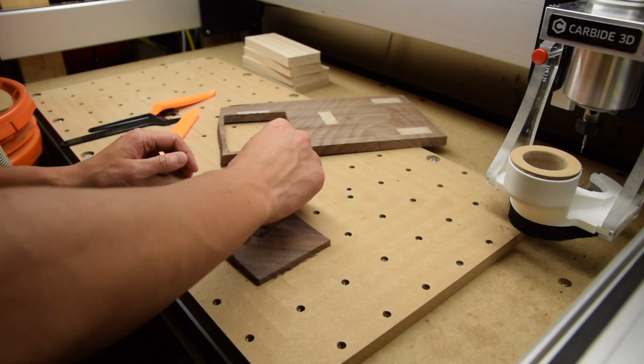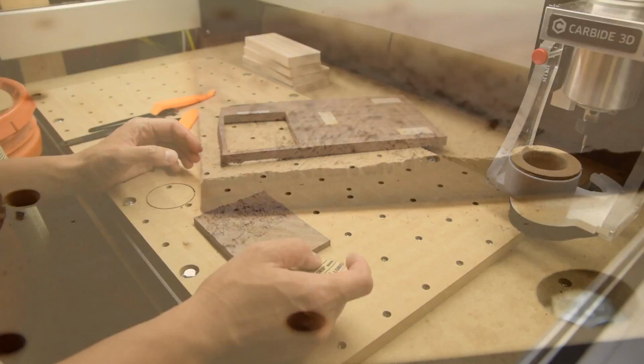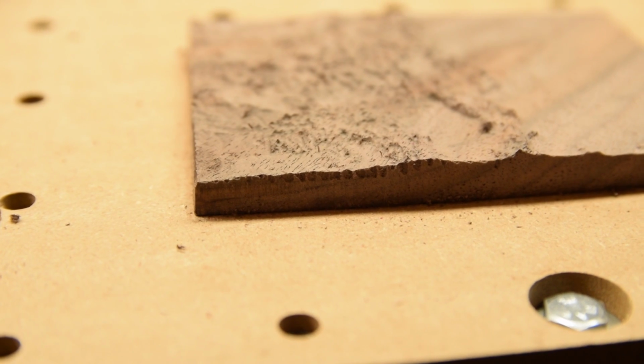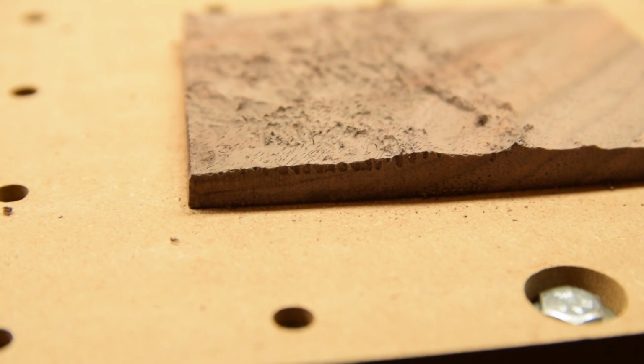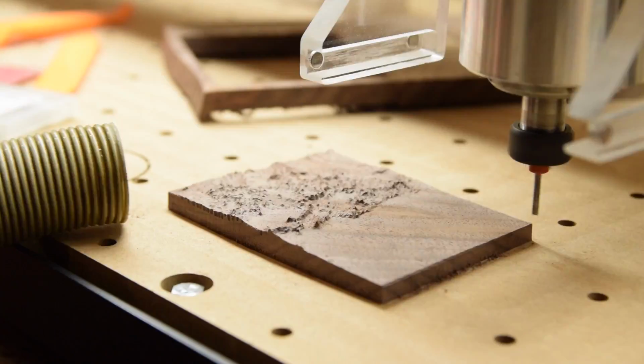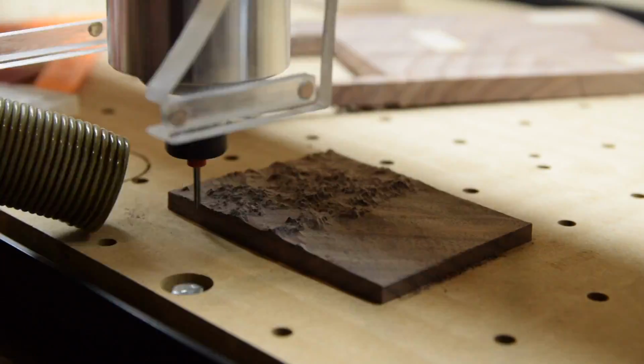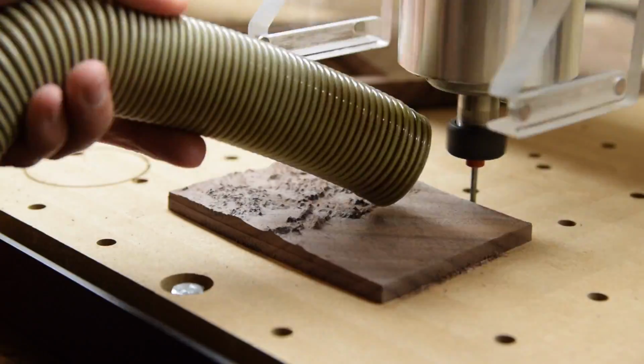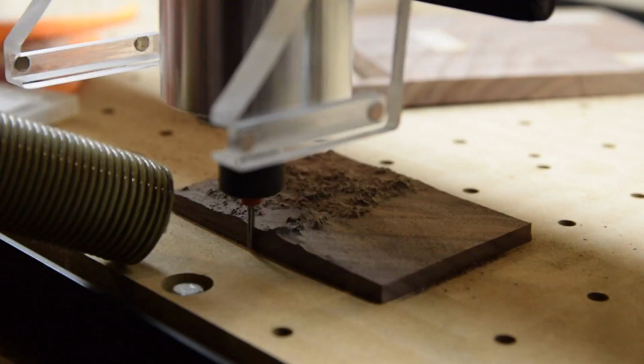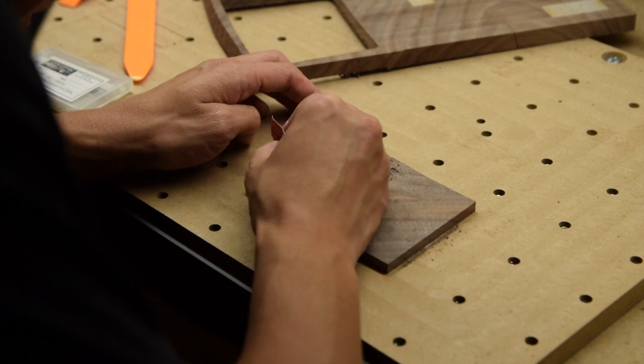After assessing the machined part, I noticed some tool marks on the sides. My parallel toolpath had wrapped over the edge of the part in some places and nibbled away at my walnut where the STL's edges were jagged. I fixed this by running an extra contour toolpath with negative stock to leave. This would cut out the sketched state outline just a little tighter. And now I was finally done machining.